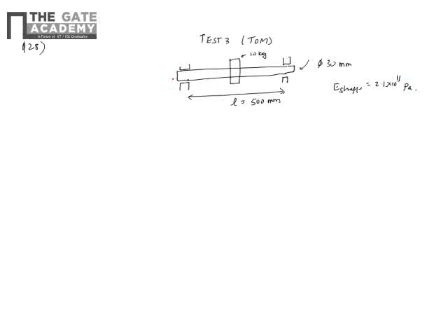Okay, so the shaft is basically an elastic member. When I have a shaft and I keep a mass, something like a rotor disc, it will bend because the shaft is elastic and it is something like a simply supported beam. When I put a load P, which is equivalent to mg, there will be a deflection. Remember, the shaft mass is neglected. The shaft is just considered as an elastic member, so I can model it as such.